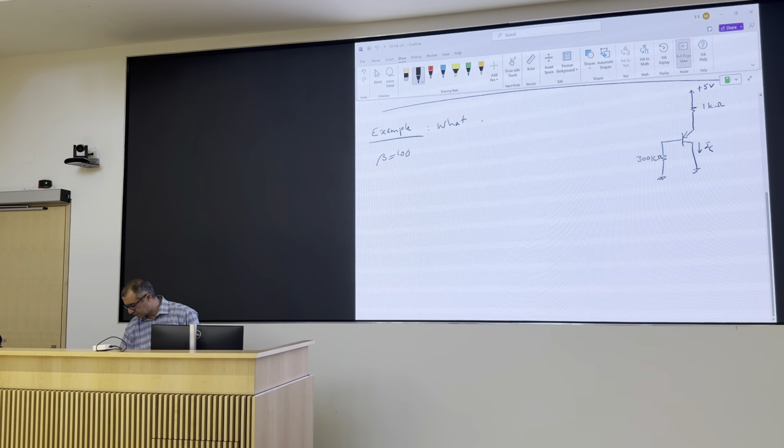You remove the probe, it's saturated again. Measurements on high impedance nodes are tricky. You have to have the right equipment for it, or you have to know the limitations of your instruments really well before you try. So I try to avoid measuring base voltages, if I can. Right? Collector and emitter, much easier.